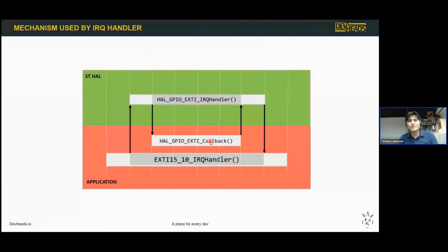And many times we don't even see behind this function, because this API exists because of the handler function, and this function gets invoked from that function. But this is the process of how the interrupt IRQ handler is processed.